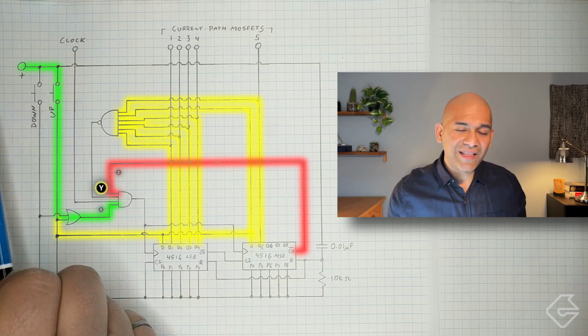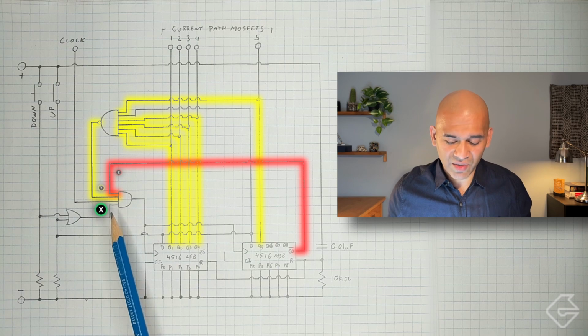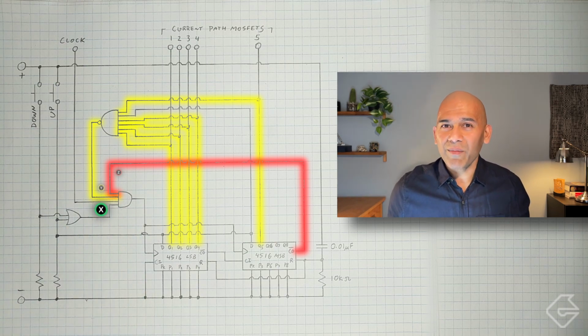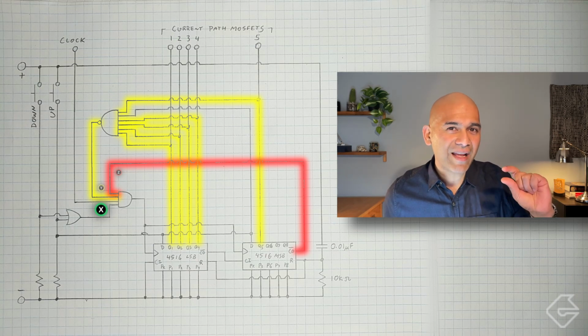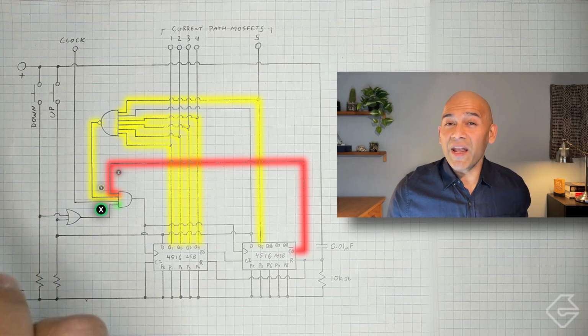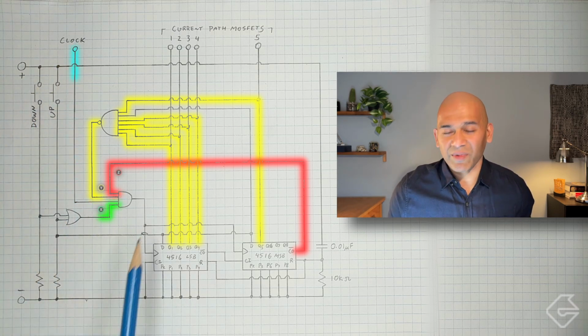As soon as I release the up button, bouncer X jumps into action and blocks the door, and bouncer Y goes away at that very same moment. But what was happening was there was a time in that transitionary period, not all the time, but sometimes, where neither bouncer was blocking the door, and the clock was able to squeak through.